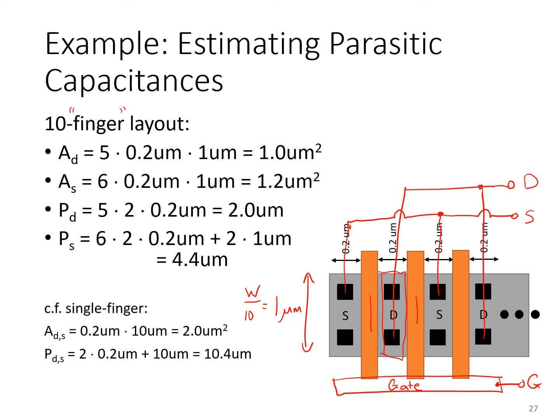But again, this insight would be required at the time when you're specifying the schematic. And indeed, any decent version of SPICE will allow you to specify parameters such as drain and source area for each transistor individually. Because the simulator can't read your mind. It doesn't know how you're going to lay out the transistor, so you need to tell it.